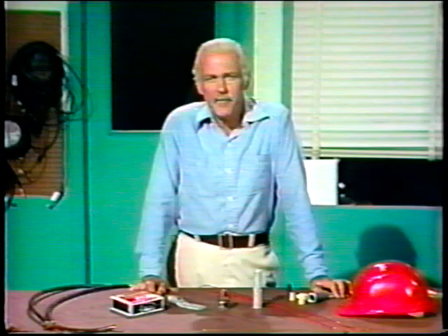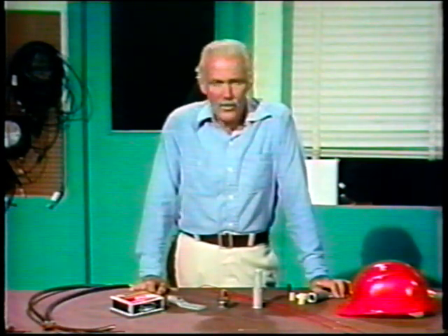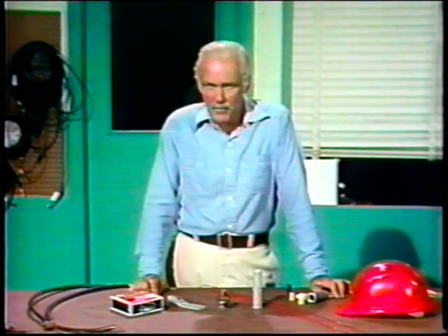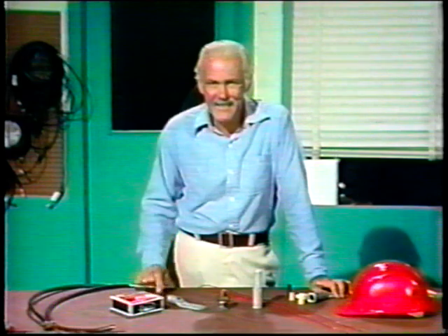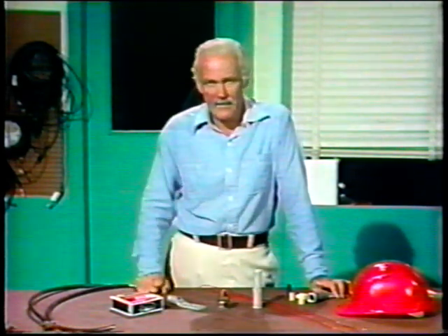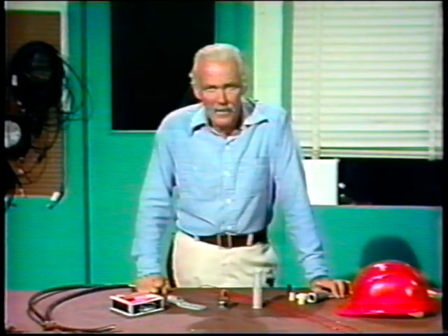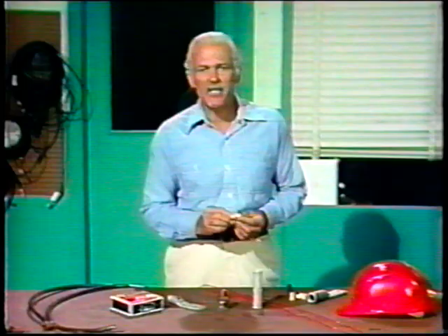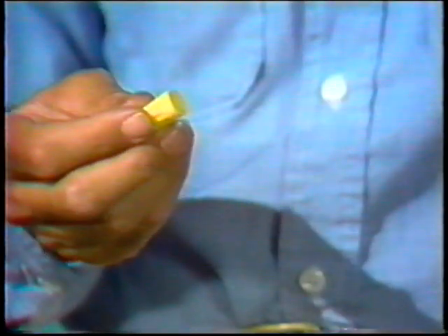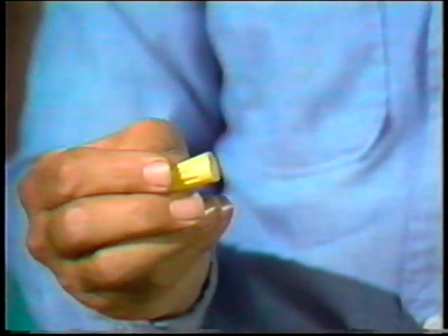Mechanical connectors use mechanical pressure to join the ends of the conductors to the connector. Your primary objective whenever you're making a splice is to make sure that you've got a strong connection. It's got to be strong in two ways: mechanically strong and electrically strong. Now, here's an example of a mechanical connector that's frequently used to splice small conductors. It's a wire nut. It's one of the simplest connectors to put on.